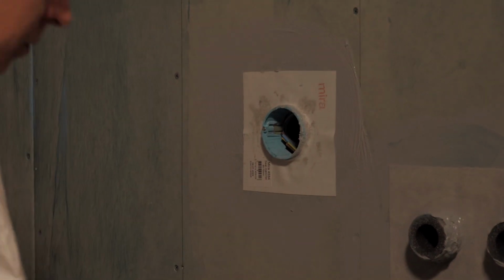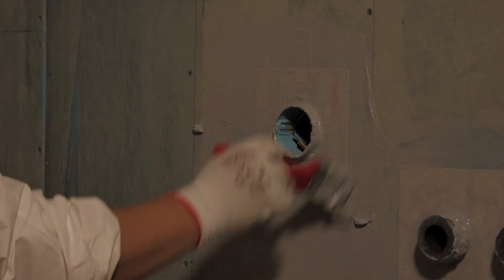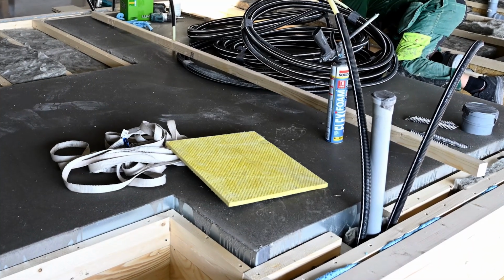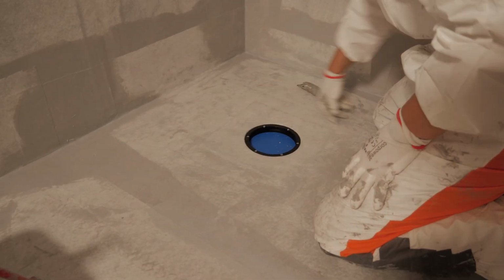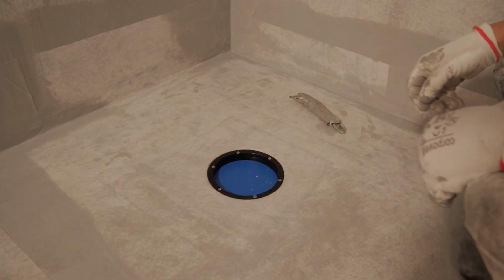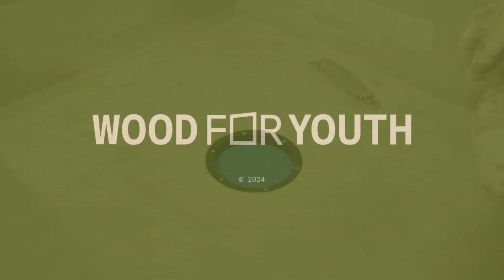Typically, a special gasket is used for this purpose, which fits tightly around the pipe or is glued with mastic to the wall's waterproofing. Sewer pipes in the shower area near the sink or toilet are located within the structure. The shower drain is managed through a floor drain. Since these drains are highly exposed to moisture, sealing around the drain must be done carefully to prevent any water leaks.